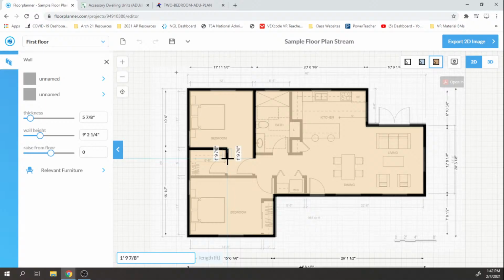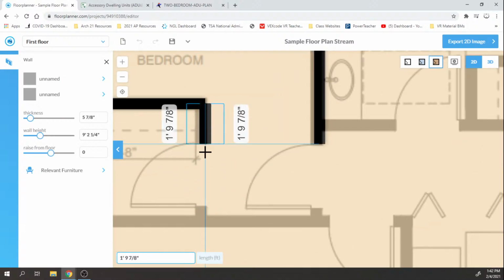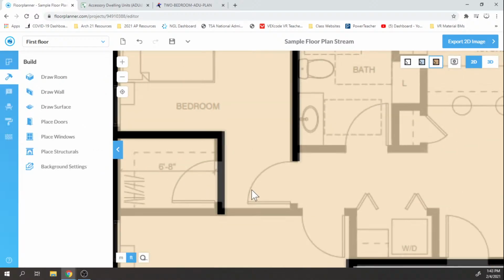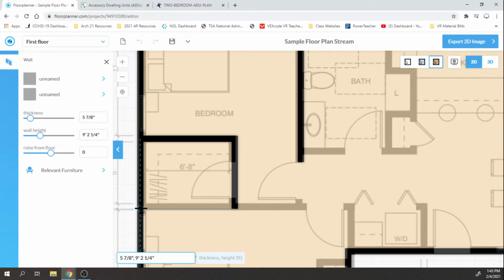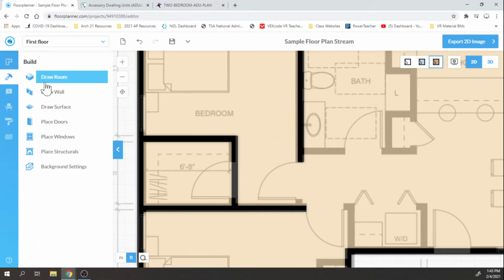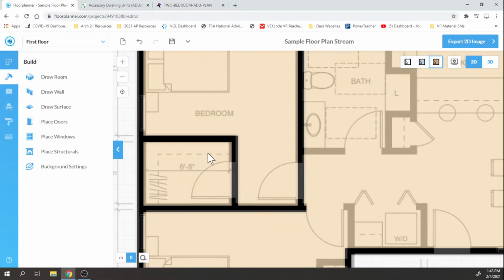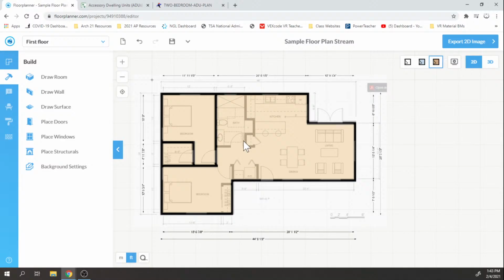And at this point, you're just going to create the general layout that you see here. Now, one of the things that I should make a point of is I'm going to go all the way across here, even though there's supposed to be a door. We can add the doors later. The doors will cut the holes in the walls themselves naturally. So if there's a door there, just draw it as if it were solid. As you can see what I'm going to do here. This specific wall should actually have been extended. So at the moment, for something simplistic, we're just going to kind of extend that. Okay, we can add a door to that later. So we would then obviously go through and pick off and add these details and so forth.